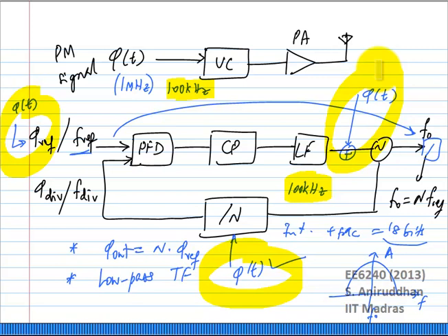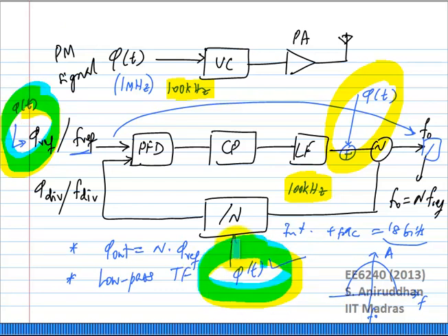How would you do it? Let's go back to our 1 megahertz case. How would you actually use this to transmit a 1 megahertz phase modulated signal? Exactly. So what you do is split the input phase modulated signal into two portions. One goes from 0 to 100 kilohertz. The other goes from 100 kilohertz to 1 megahertz. Right? So the low pass signal will actually be sent through this path or this path, and the high pass portion of the signal will be sent through this portion.